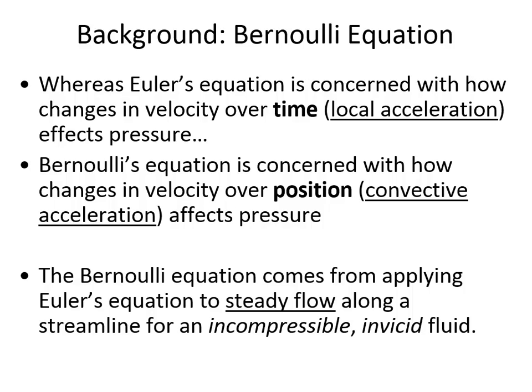We'd have a spot here, we had a spot there, and as it was converging again, there were all these little tubes. These were piezometer tubes, and so maybe we're close to the same streamline, but not exactly. If there's turbulence inside of the pipe, then we may not be along the same streamline. And so Bernoulli's equation is more accurate for laminar conditions than it is for turbulent conditions because it's more challenging to measure conditions along a streamline in turbulent flow.